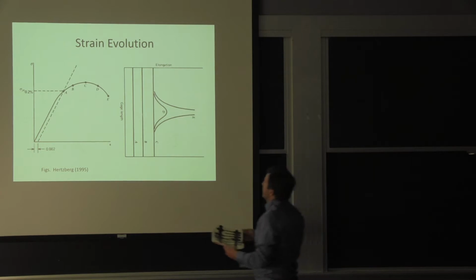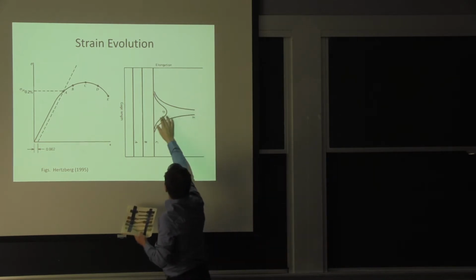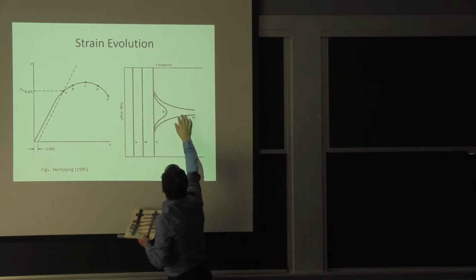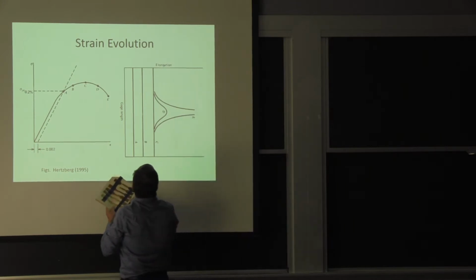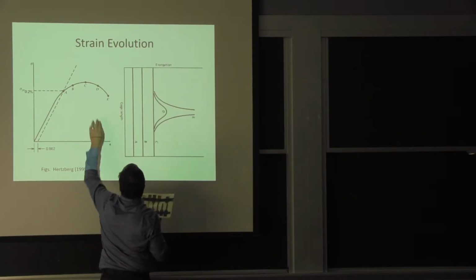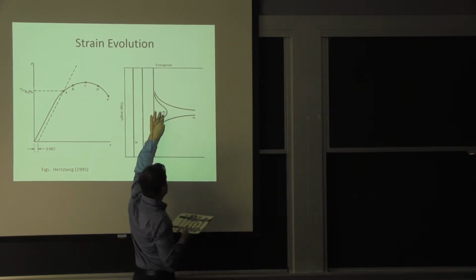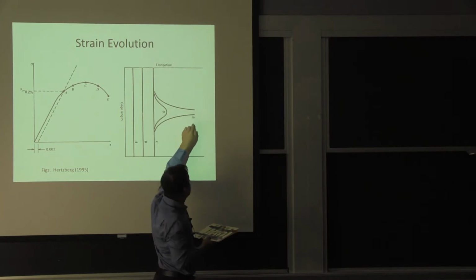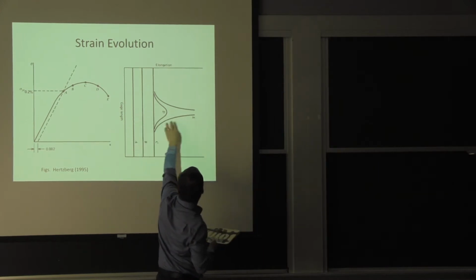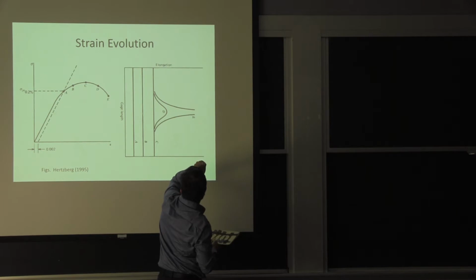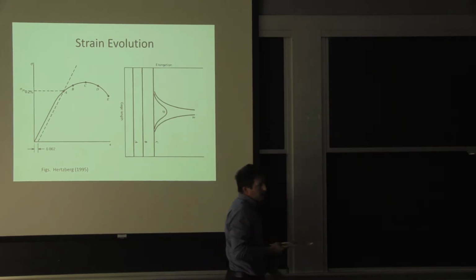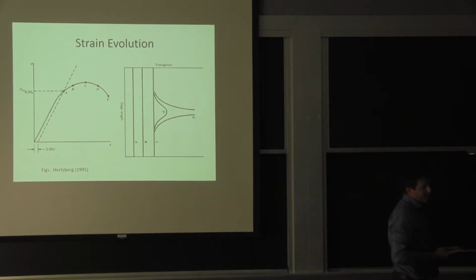If we say that the necking is going to happen right in the middle of the specimen, after you passed the stage C here, when you're at D, you have all the extra plastic deformation taking place in that neck, and it keeps going and going, so that your strain level is much higher. Typically, the total strain is going to be about twice what it is in the neck than it is in the remaining section of the material.